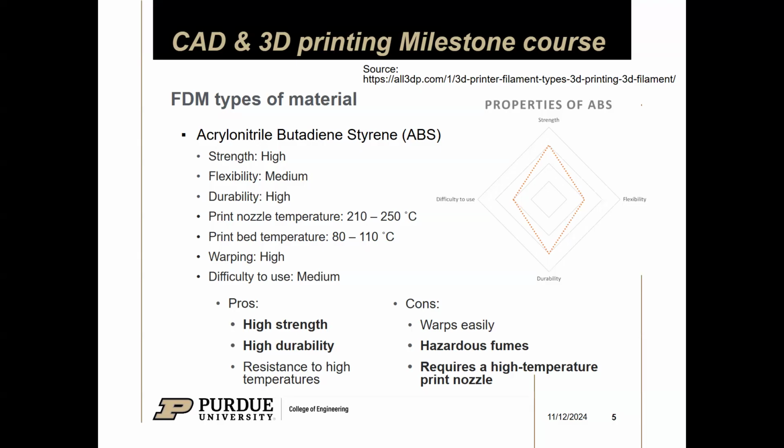So a lot of plastic pieces that you'll get from like a factory are usually 3D printed. I mean, not 3D printed, ABS. So stuff like Lego and stuff like that is all injection molded ABS. So it's a pretty great material. It's got a lot of great properties. It's very strong. The gantry on this printer is printed in ABS, so it's pretty good material. Because of these high print temperatures, it can withstand like warmer environments, which is good.